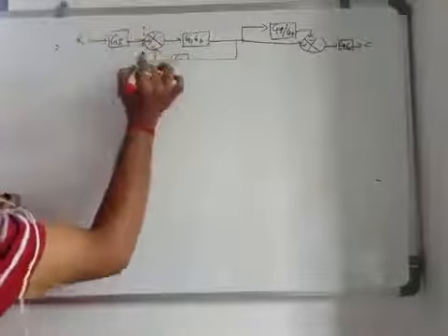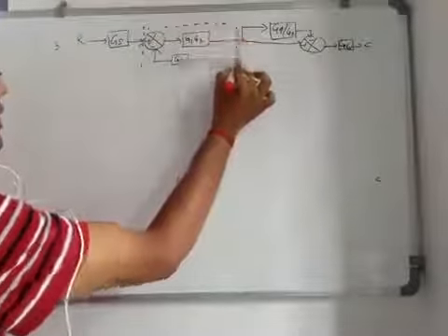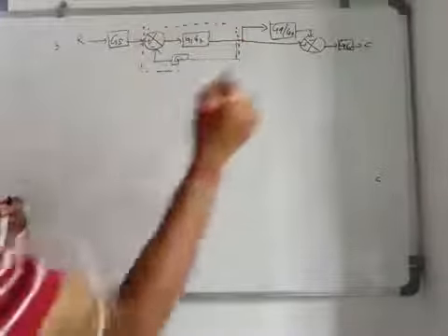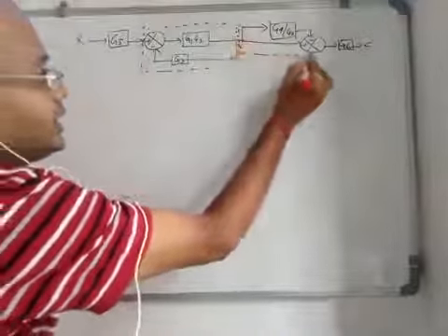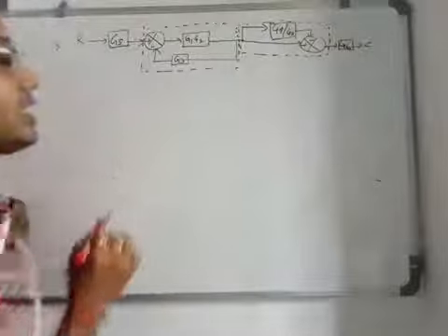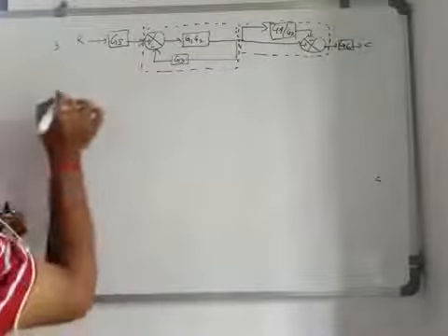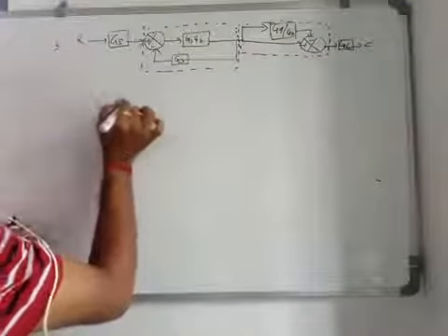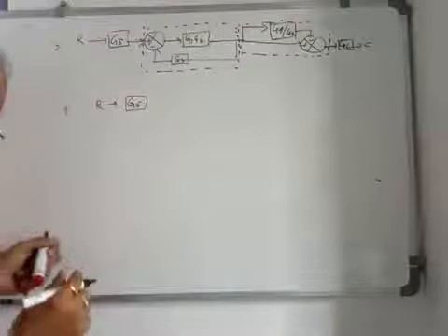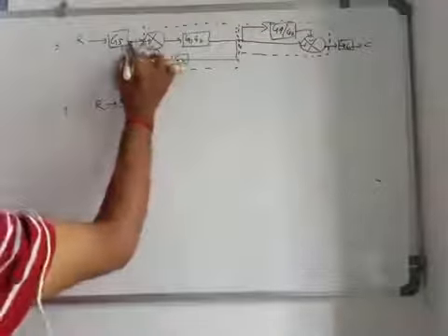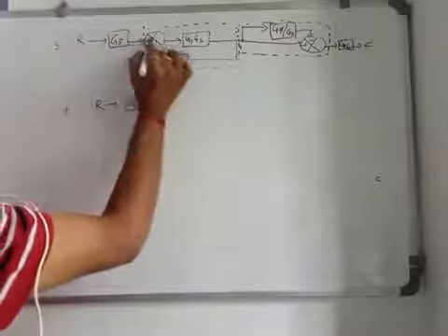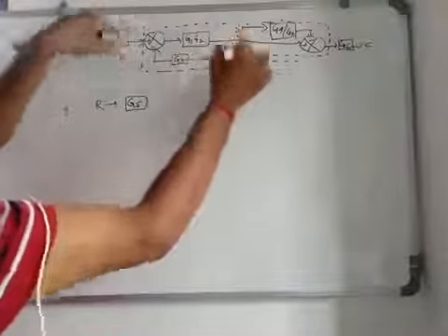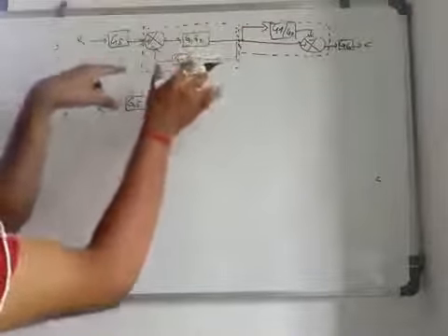In the fourth step, you will just find out the normal loop like structure. So this is our desired. There is a loop, and here you see there is again a chance of reduction. So in a single step we will do the 2 steps output, that means step 4. This is your R, this is your G5, and what is this? This is the feedback path G3. Signal is going there, so here you get a closed loop feedback path, right?